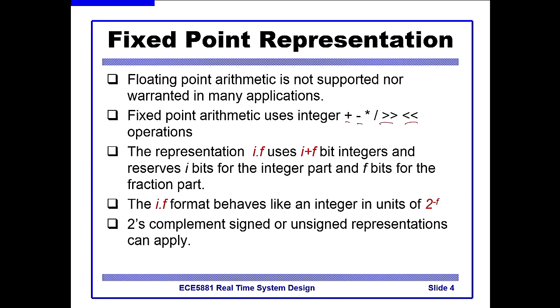All right, so the division is not something that you're probably accustomed to, so we'll need to discuss that in a little more detail. But the basic representation is you have integer bits, say 10 bits, and you might have F fractional bits, say 6 fractional bits. So 10.6: that's 10 integer bits, so you can go up to 1023, and you have fractional bits of effectively 1/64th of a unit in your system of arithmetic.